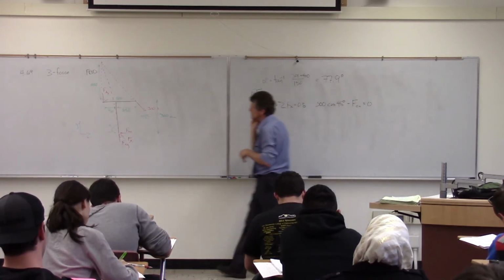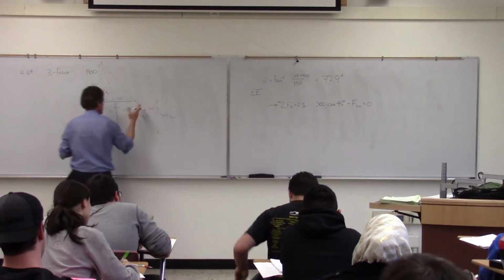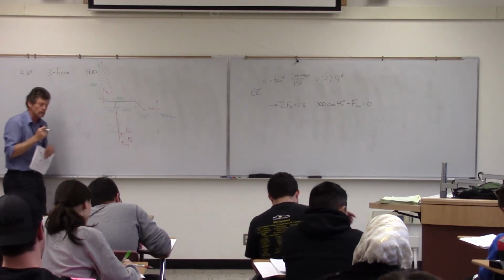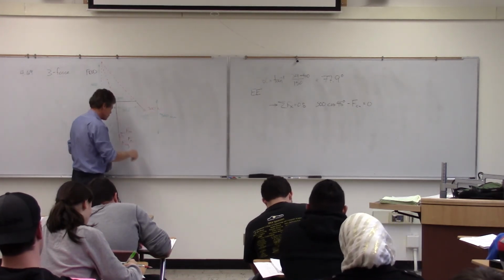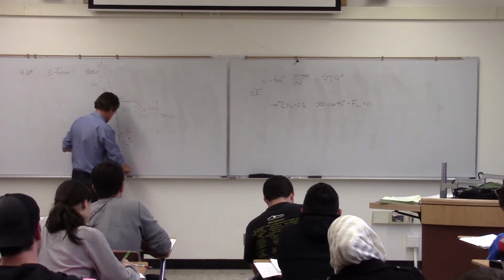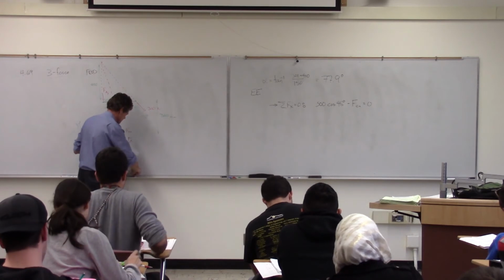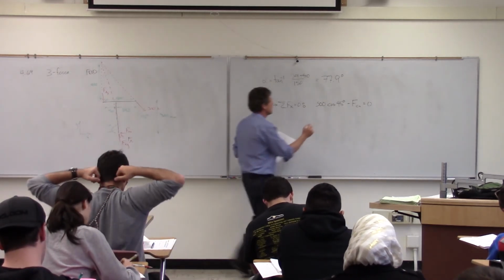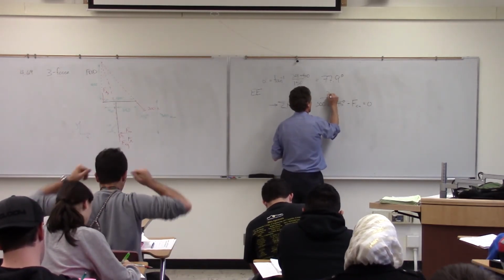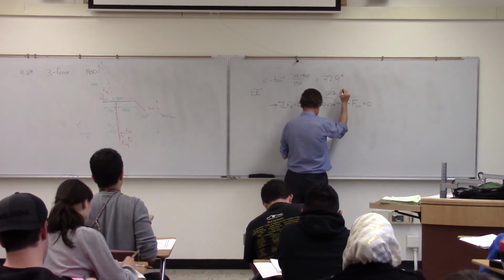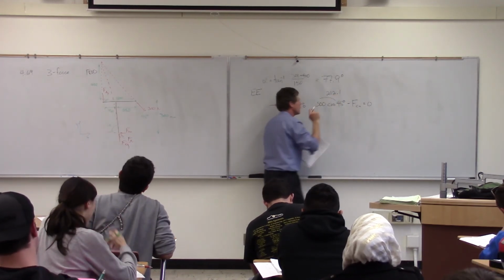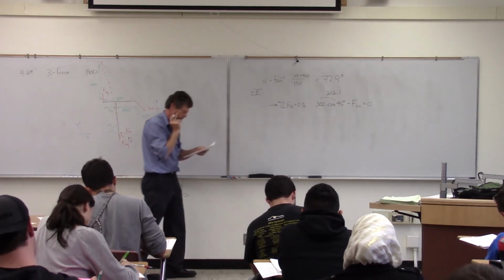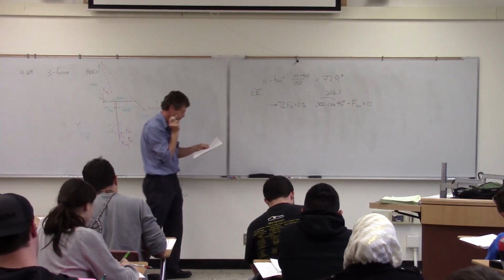So just in terms of summing forces in the x direction, I'll have two components there, the 300 times the cosine of 45 degrees. If I measured it from there, actually that should be the sine, but it will be the same regardless. That'll be 212.1 newtons.